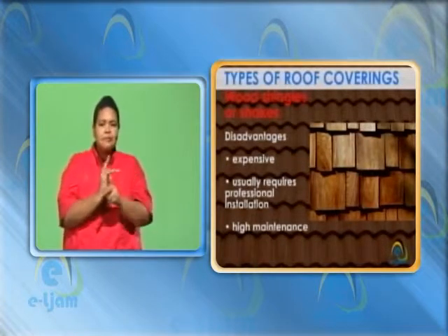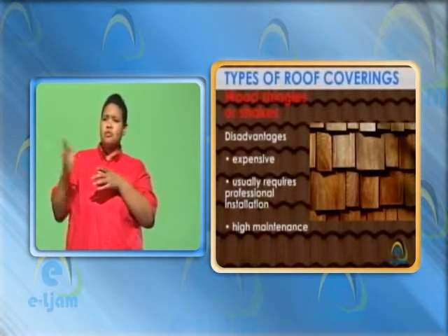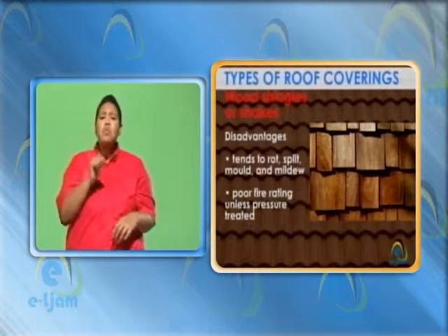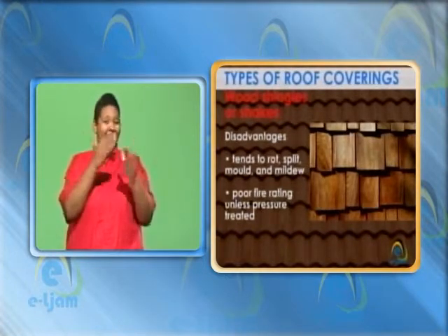Disadvantages: expensive. Usually requires professional installation. High maintenance. Tends to rot, split, mold, and mildew. Poor fire rating unless pressure treated.